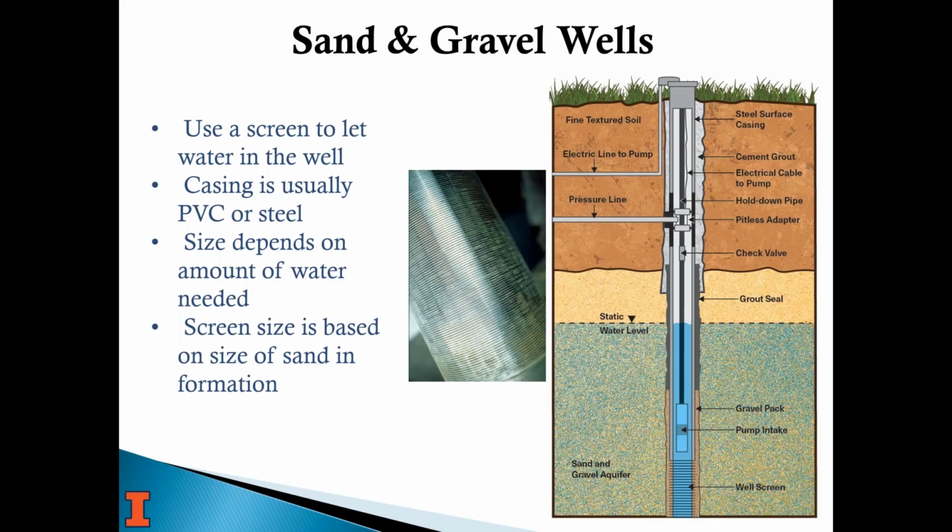And they also put in a gravel pack, which you can see in that diagram near the bottom. The sand is a different color right around the well, because a gravel pack is a very uniform, set-sized sand that you put around the screen, and that also acts as a filter to keep finer sand from getting through into your well, all the time letting water still get in as you pump it.